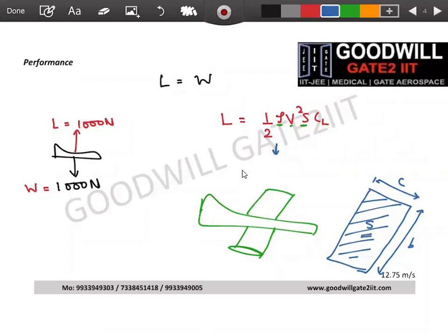Now there are different areas, like wetted area and cross-sectional area, that we'll talk about. There are different areas which will come in different equations. But whatever area S you will see here is the planform area. Whatever you see from the top, you don't worry about the slopey thing, because you are using your NACA foil here, right? Don't think that we need to capture this curve to calculate the area. Anything from the top, that area should be considered here.